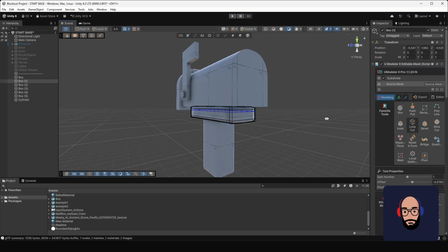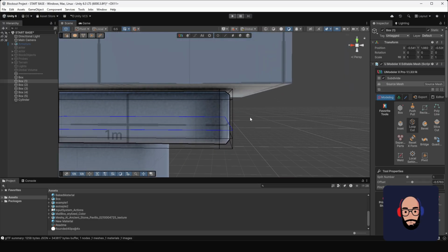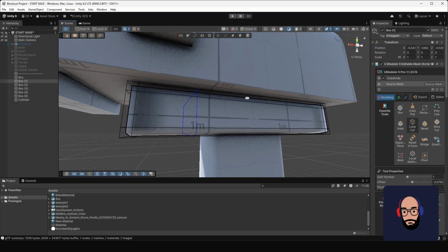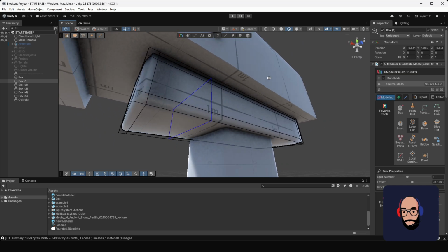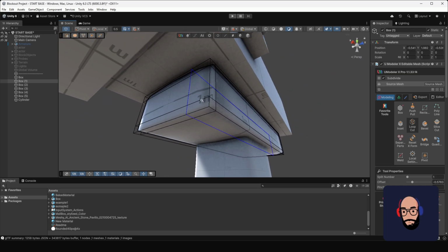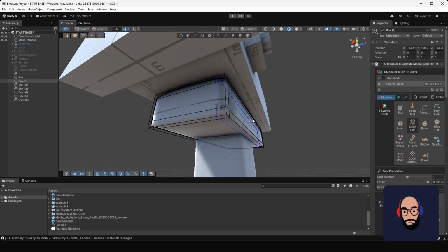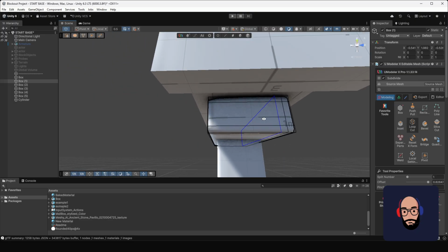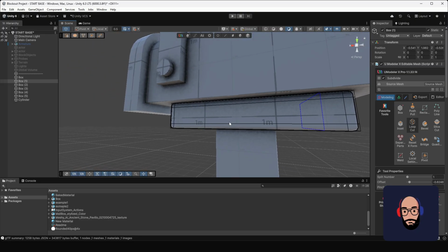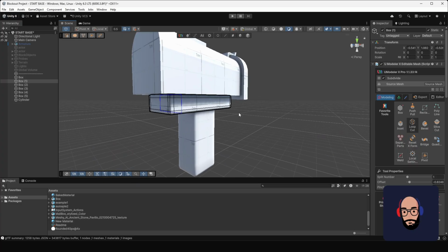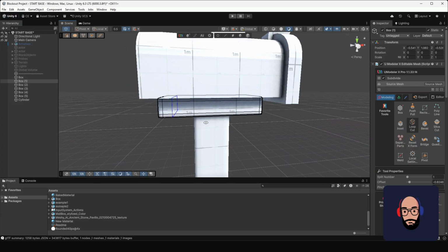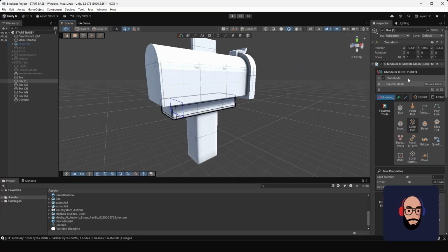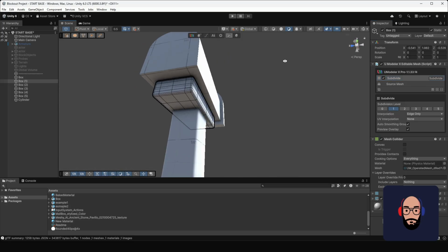So I'm going to go ahead and add in all the edges I need just to make sure that it looks like the piece of wood that I expect. So we need to constrain it on this edge here like so, and also constrain it on this edge as well. So that's going to look much better, and it keeps our poly count still down. It's not too high. Great. So we go back into subdivide, and there you have it.